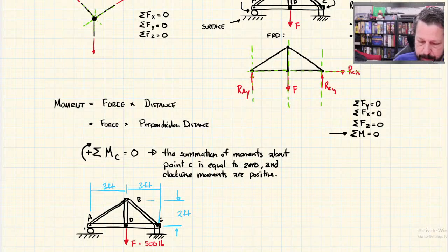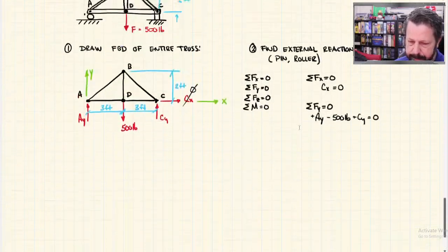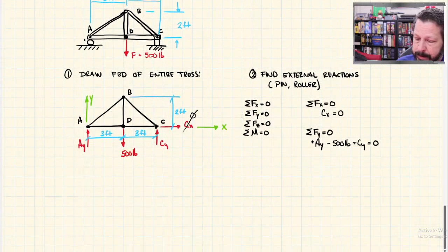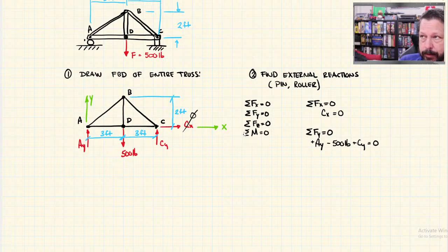All right. So what did I just say? I just said that the x, y, and z equations are not helping me. The z is not helping me. And so I need something else. We have recently added the idea that not only do I know that this free body diagram, the one in the center of the screen, is not moving in x, y, or z, but there's no point on this diagram that it's rotating about. So I can say that the summation of moments equals 0.